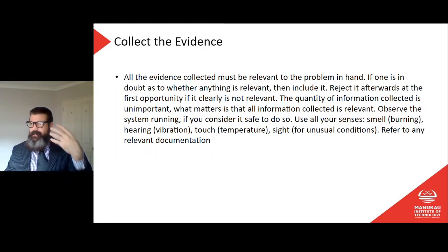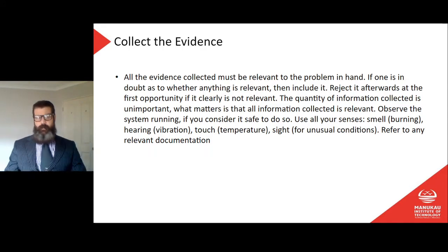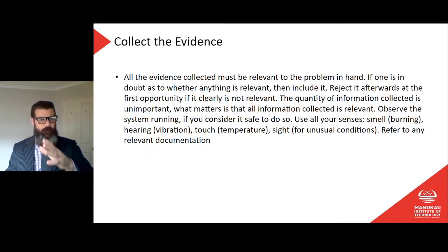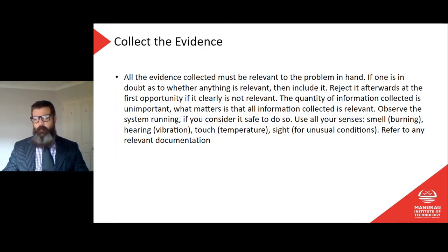I'm giving some specific examples, but if you use that as a concept, you will find it a very useful thing. Like, what is the common feature here? Because sometimes you'll have some things that seem quite different, quite unrelated, 2 faults, and you go, oh, how are these things related? And if you have a think about it and go, well, where is that power from? Where is that controlled from? Suddenly you go, oh, actually, all of these things are powered from the same emergency stop switch. Okay, let's have a look there.